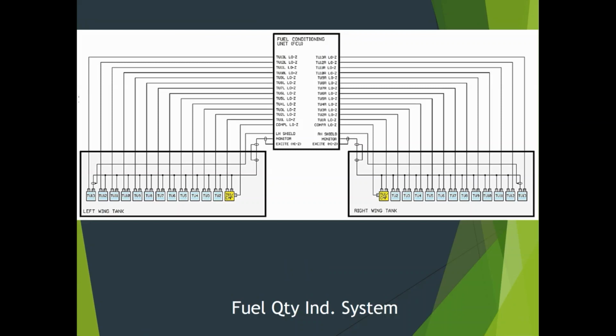Why is this on more modern aircraft? Why not just wire them all in parallel? So in this case, well, if one is screwed up, you can identify it. On the planes I worked on where they were all wired in parallel, if we were having a fuel quantity issue on one side, we knew it was on one side. And then we had to go test each probe to try to figure out which probe it was. And they have special test boxes for these that hook up and do capacitance. You don't use a regular meter on them. We've got one over there.